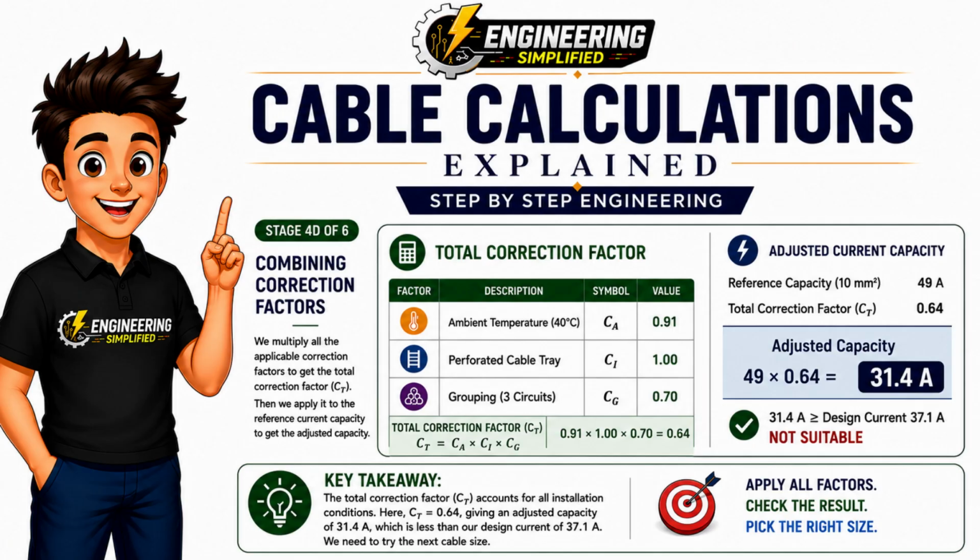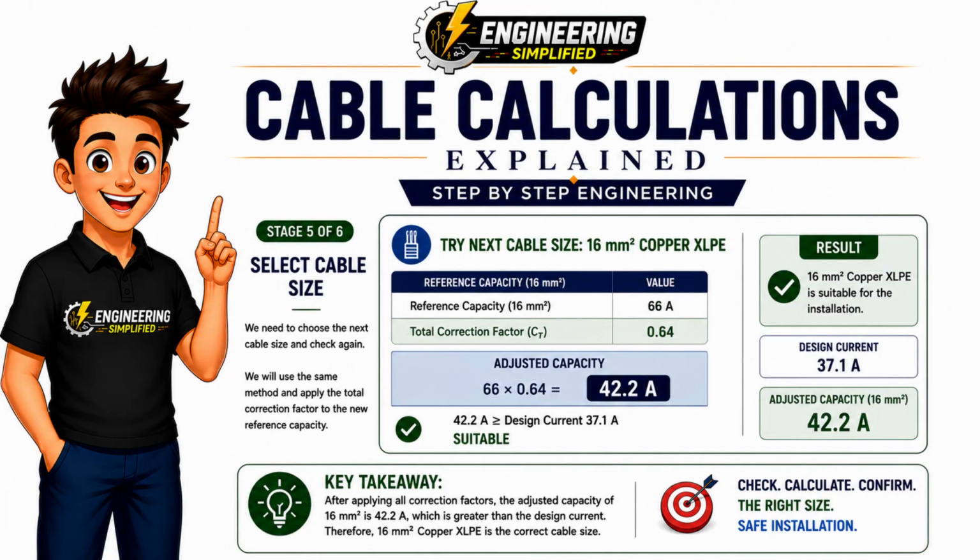Although the cable initially appeared to meet the design current, the correction factors revealed that it cannot safely carry the required load under the actual installation conditions. The next step is to increase the cable size and repeat the calculation. Using the same correction factor, we check the next available cable size.